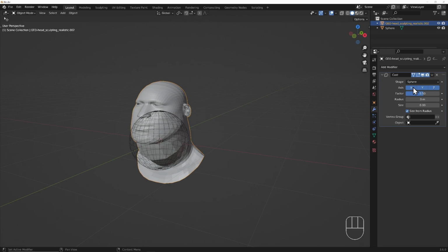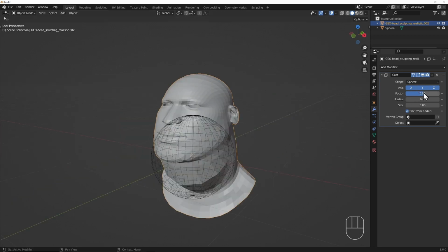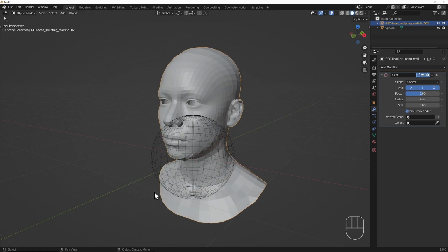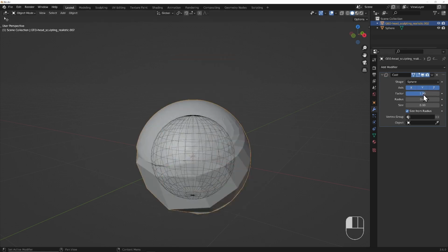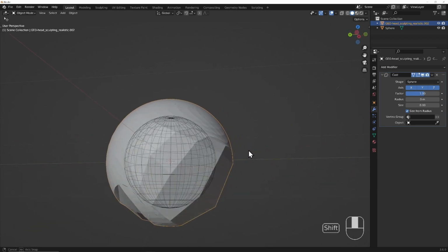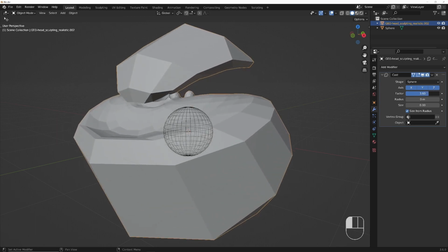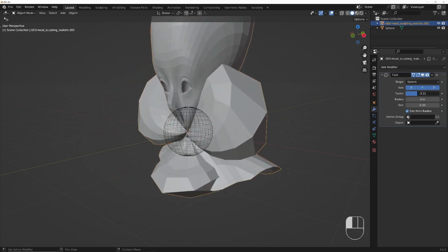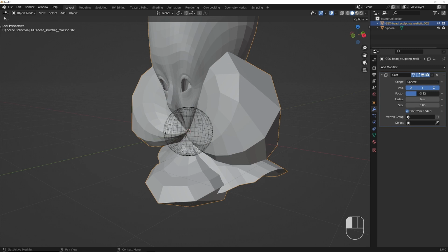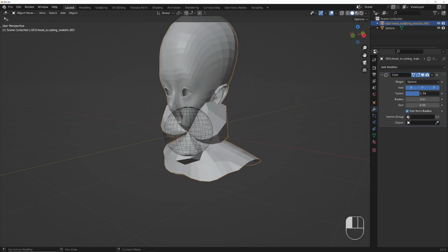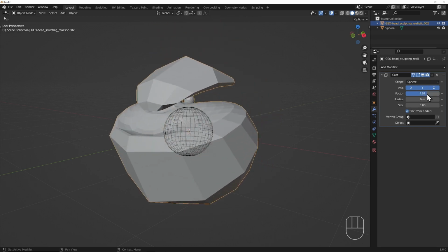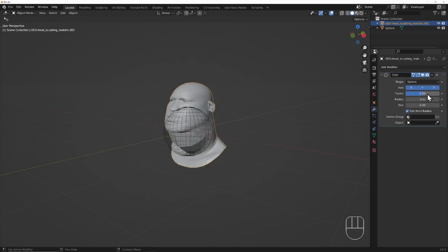The factor is set to 0.5 by default. Now, this is midway between 0, which will have no effect, and 1, which will show the shape that the mesh is deforming towards. Pushing the factor beyond 1 or below 0 can cause some interesting or unintended effects. This is because the transition is mapped along a linear gradient, and therefore it will extrapolate the position of each vertex and will push it further along that curve.